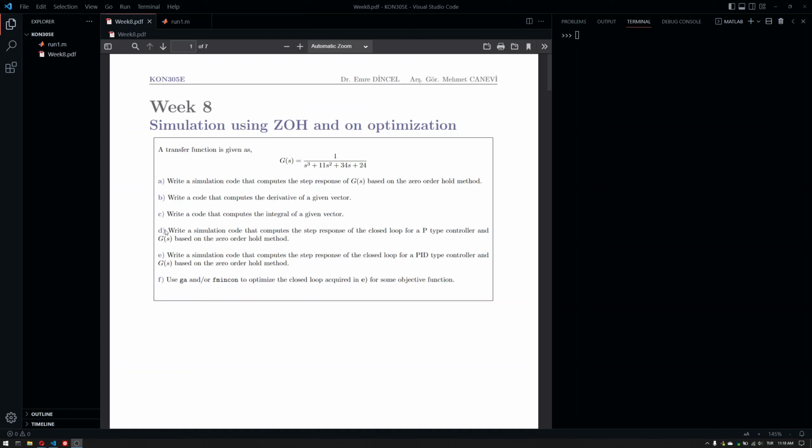First, the problem is to convert this transfer function into a more usable representation. For that, we will use basically differential equations, but we're not really using high-order differential equations for simulations. It makes more sense to use low-order differential equations. For example, we have a third-order system here, but ideally what I want to have is three first-order differential equations, because this would be a third-order differential equation.